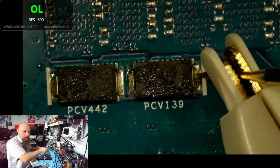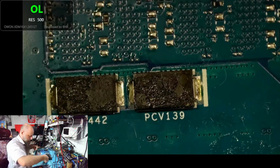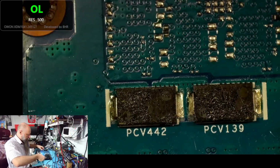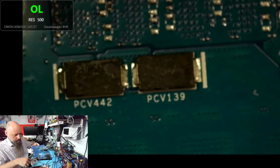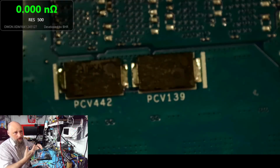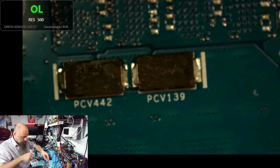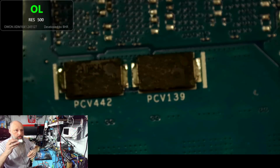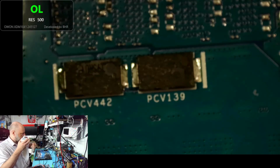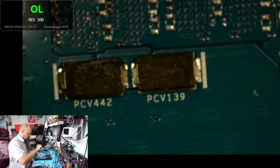Okay, so we got 130 milliohms on this one, the original, where we expect the GPU works. And we have around 178 on this one, so roughly the same, very roughly, but I conclude that the GPU is fine, meaning the core is not shorted. So now, let's do this.